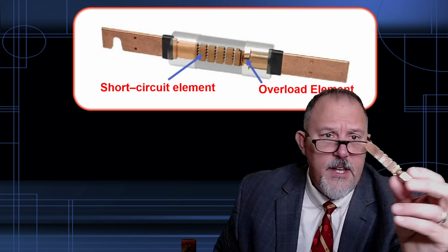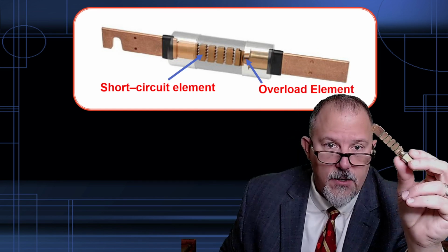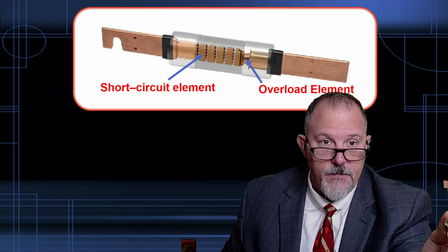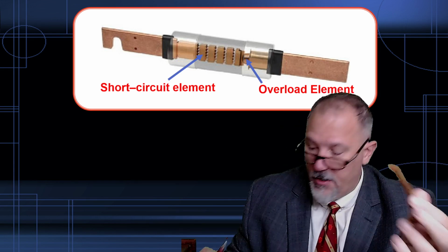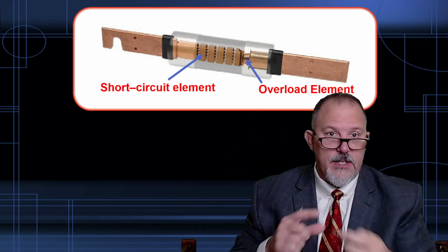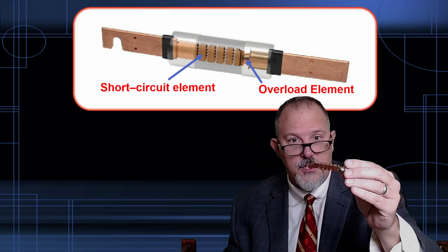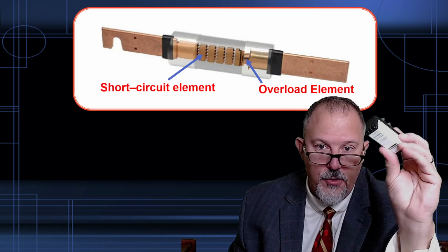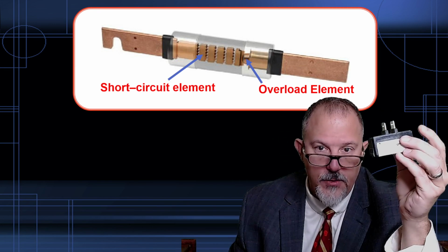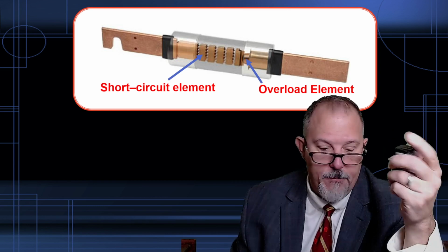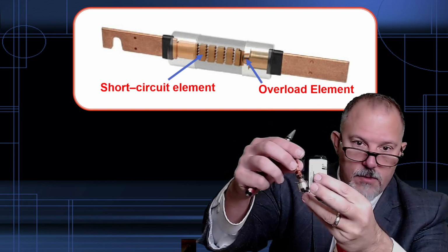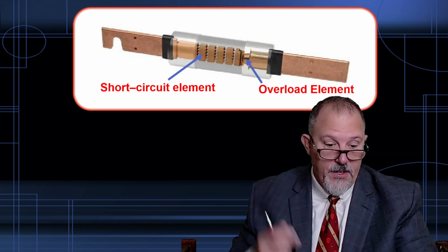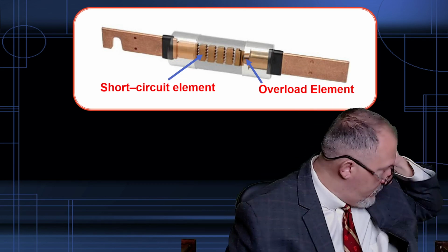Now, this device here is what does the work to open the circuit. And depending upon the fuse, in this fuse here, it is a cylindrical. That's typically the way this is put in. In some cases, you might have what we call a cube fuse, which is a square fuse, which is a little different format, but this element resides in this fuse just like that in a different configuration.